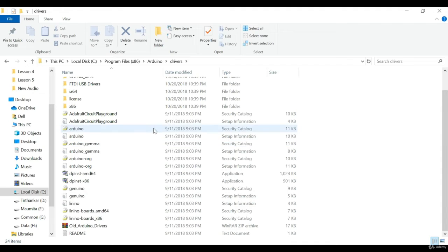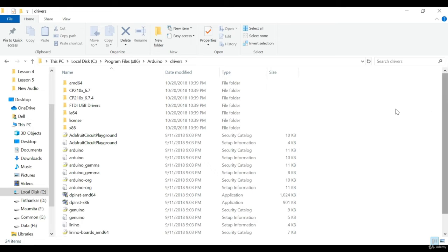If you install Arduino IDE, you will get these drivers. So in any case, if you connect Arduino with your computer, you will get a COM port for sure. And if there is some unknown IC that the manufacturer has used, then you have to install the driver externally. There must be some process to download the driver and install it. But this is the standard method through which you can get your COM port.